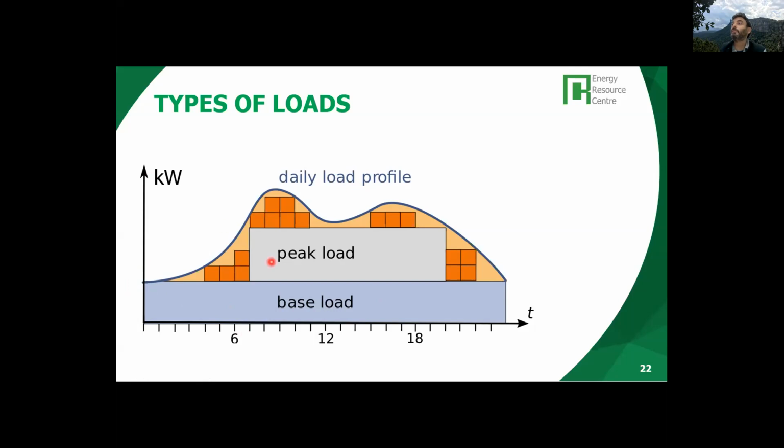And then the peak loads are important to decide what kind of inverter, what kind of generator, even a backup would be possible to cope with this peak of demand. Remember, we could have different load profiles for different days in the week. There could be a different weekly pattern for Saturday or Sunday, weekends, Friday, I don't know.